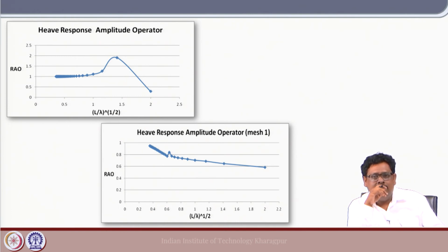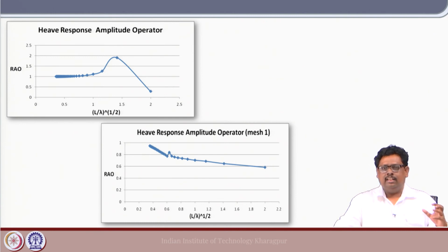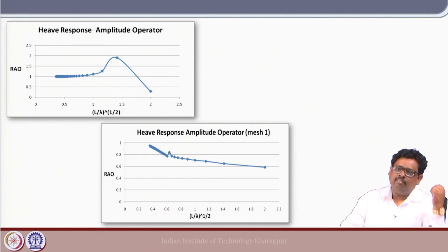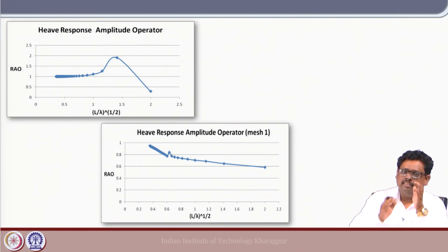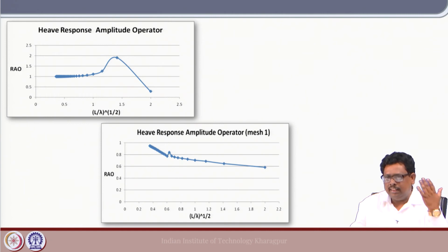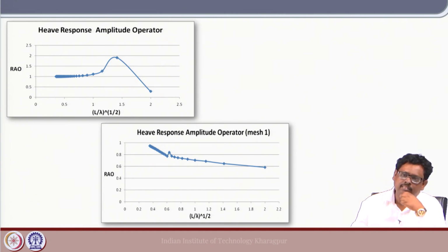in the lower frequency range both approach 1. I mean, it is a heave response. That is how it should be, right. In the lower frequency range it should approach 0, because we discussed a lot in seakeeping also that in the lower frequency range the added mass and damping do not play any big role. The only thing is the restoring coefficient and the exciting force, which is essentially the Froude-Krylov law, because at that point the diffraction force also goes to 0.